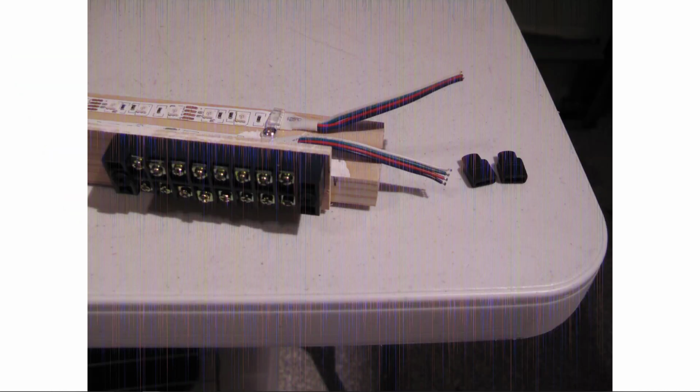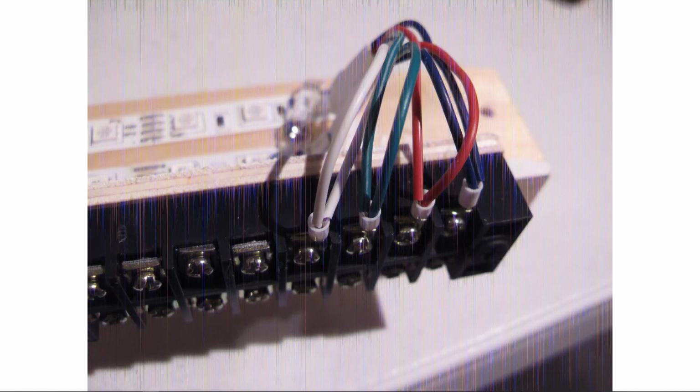What I did, and again, I didn't know these pictures were bad until days later, when I go to use them in this lecture, and they're damaged. So I couldn't even use some of them at all. They were that bad. These are good enough to get by. So I cut the connectors off the LED strips, and then I put them together in a ferrule and then clamped them down to a terminal strip. Now I'm using 8 terminal strips because I didn't have any 4s. You only need 4 terminals.